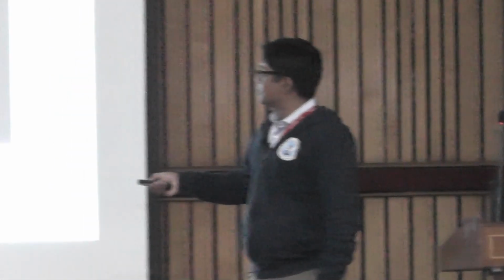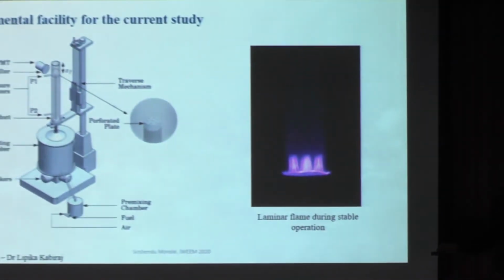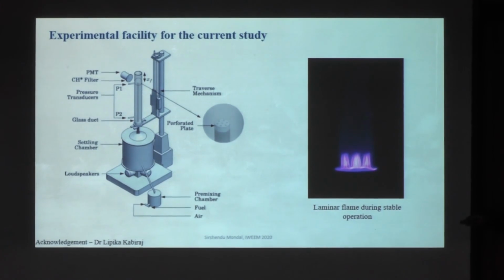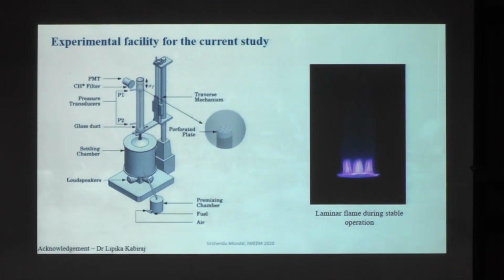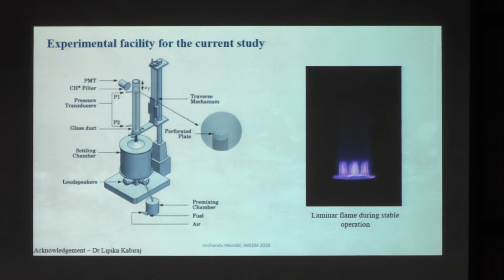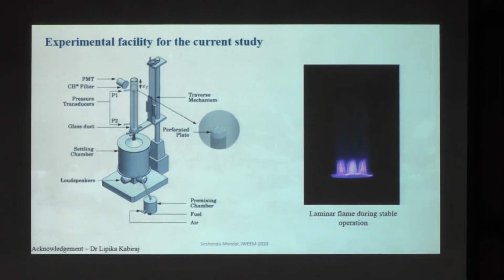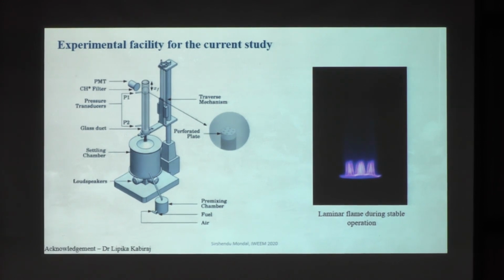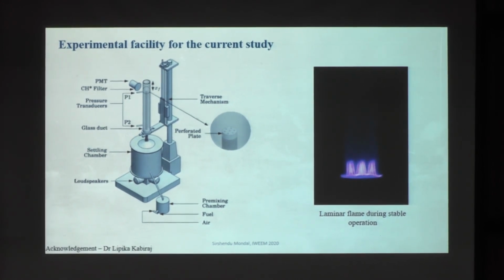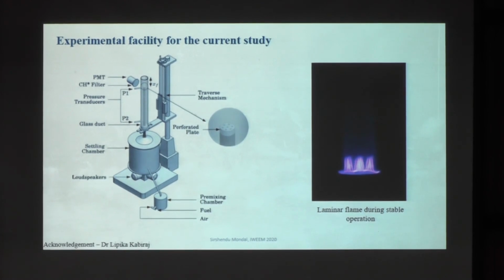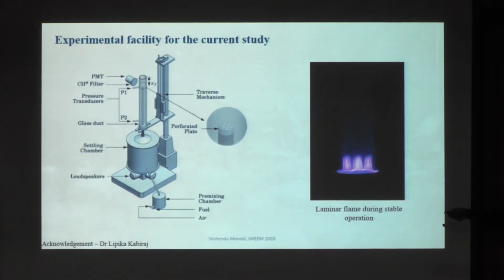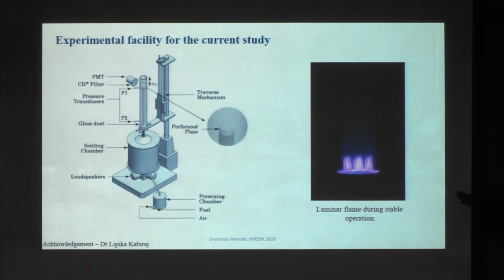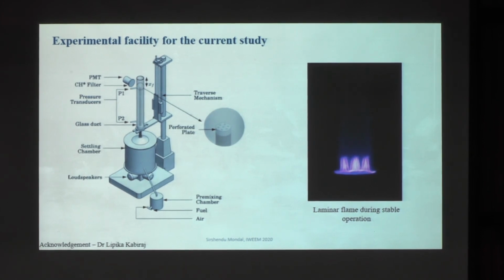So we are perturbing the inlet flow, and in that way also we got the same kind of results. But here the complications are greater because the heat release rate plays a different role. The heat release rate has a different preferred mode, and because of that the mode of heat release rate determines where the asynchronous quenching, or the maximum mitigation, is possible. This strategy can be applied, but this is again a very simple setup, so a turbulent combustor or an actual combustor is yet to be tested.